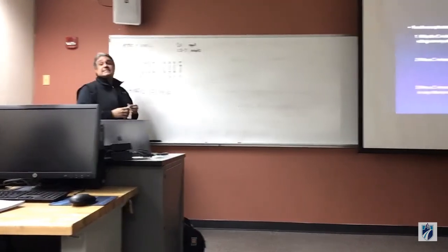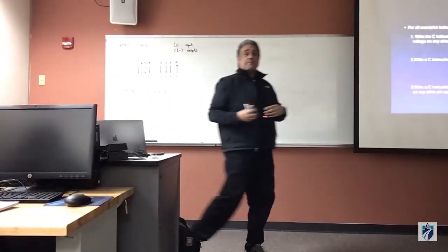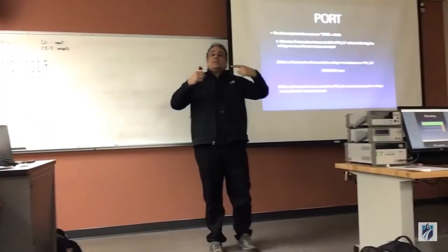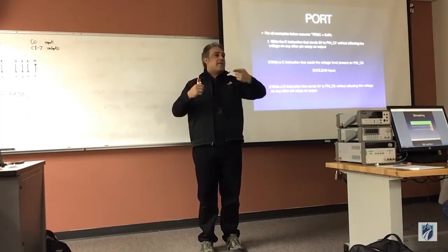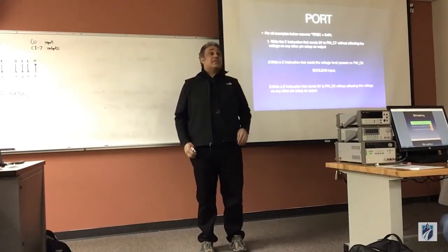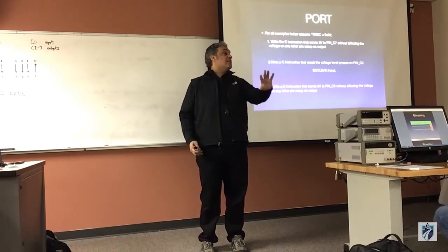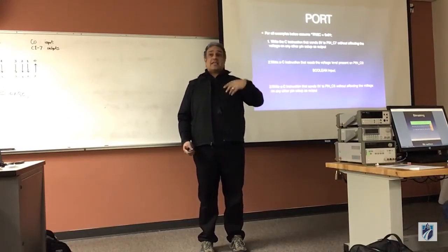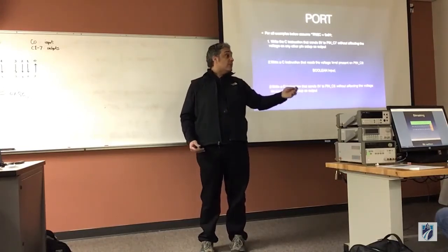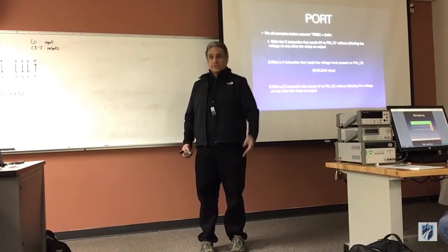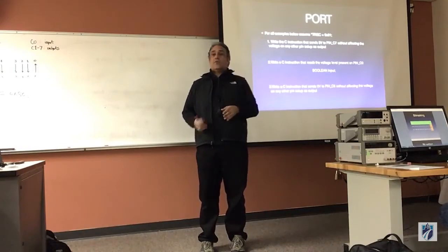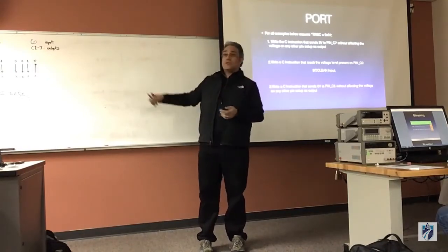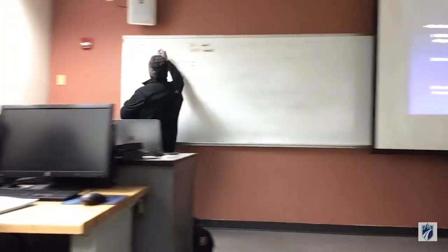The number one mistake that I tend to see in exams is we tend to miss the difference between a tri-state behavior and a port behavior. Sometimes I ask, can you put 5 volts on the output? And then we use the tri-state to do so. The tri-state can't put 5 volts out. The tri-state can only do input versus output. That's all it can do. It can just handle direction. But if you want to drive voltages, you've got to use a different circuit.